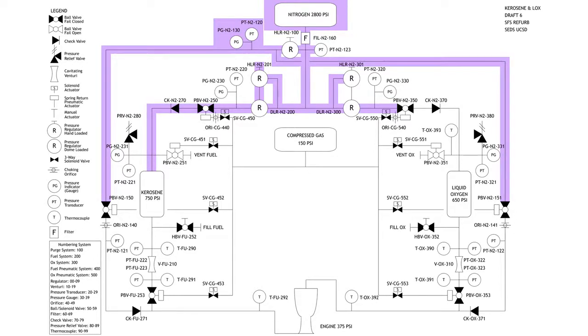So that's going to be open, and you're slowly going to start like 5 psi. 5 psi will be sitting on top of my kerosene now, and then 10 psi, all the way up, slowly and slowly, all the way to 750 psi, which means that you're going to have someone with their face and their body right next to a 750 pressurized system. That's a safety risk we're going to have to take, but that's just the reality of it.